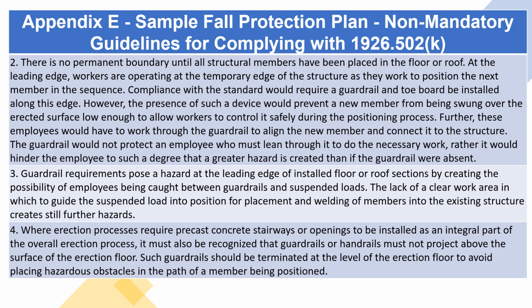Where erection processes require precast concrete stairways or openings to be installed as an integral part of the overall erection process, it must also be recognized that guardrails or handrails must not project above the surface of the erection floor. Such guardrails should be terminated at the level of the erection floor to avoid placing hazardous obstacles in the path of a member being positioned.